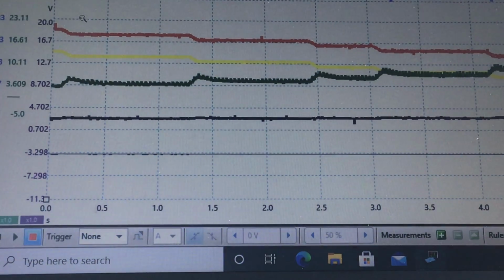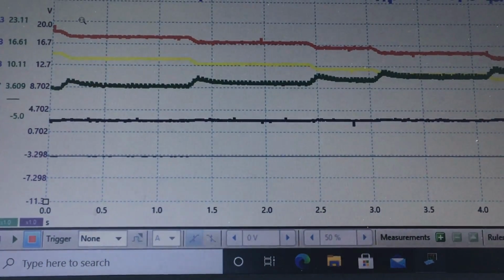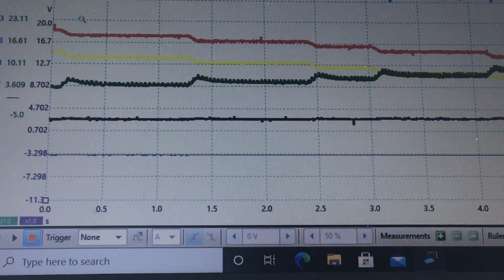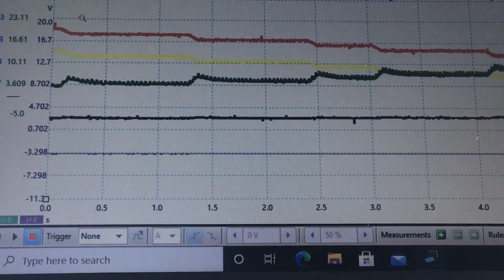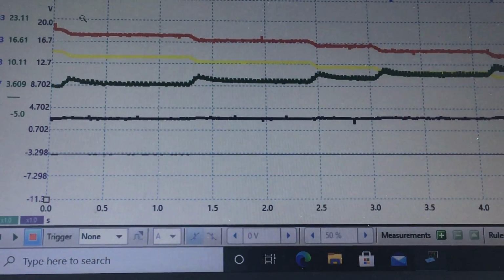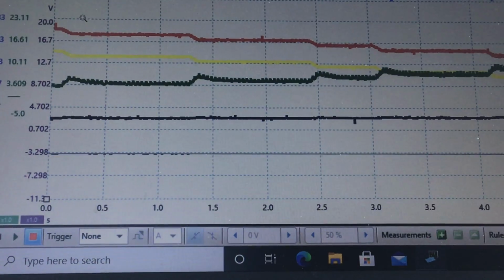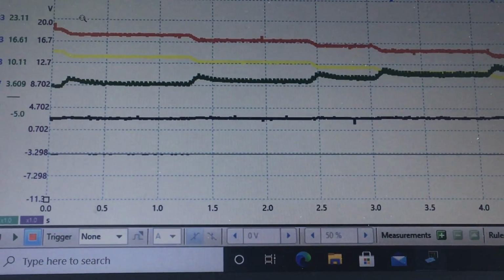Anyway, I hope you enjoyed this video. Just bear in mind cause and effect when excessive current's flowing. Look at that whole circuit and see what else you may want to recommend when you diagnose any motor, cooling fan motor, blower motor, fuel pump, and think about the relays and the components in that circuit.